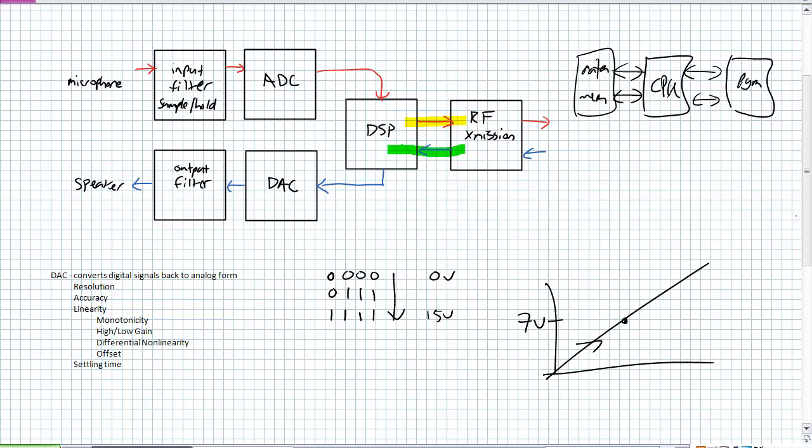Any deviation from that typical linear structure, think about this term of monotonicity. As I progress from quadruple zero up to quadruple 1, I'm constantly increasing in nature, whereas non-monotonicity is basically I'm going up and for some reason I step back. Basically, that's what a non-monotonic error is in perhaps a digital to analog converter. And this could represent perhaps some particular bit position that is constantly stuck at 0 or constantly stuck at 1, or basically some error within our digital to analog converter.